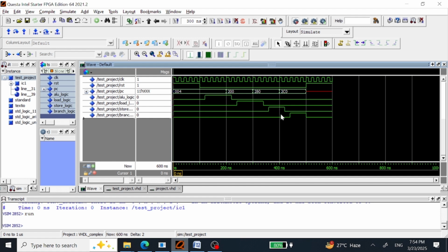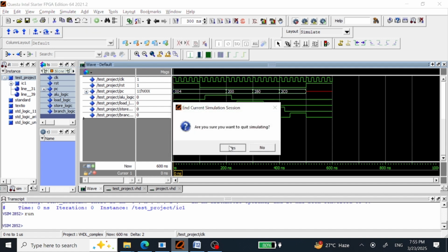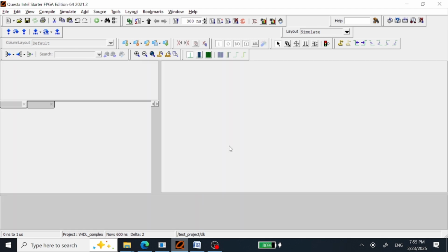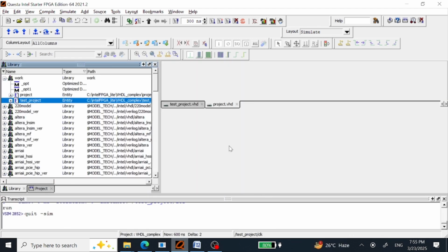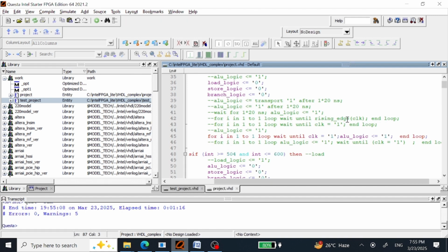And here you guys can see, we saw this even in the case of SystemVerilog as well, this fourth one was getting just 2 cycles delay. So here it is also showing some weird behavior. This is odd behavior. This was the case which we saw once when we were doing SystemVerilog as well, if you remember. The first 3 signals were getting the same number of clock cycles which we wanted to give, or the delay which we wanted to get, but